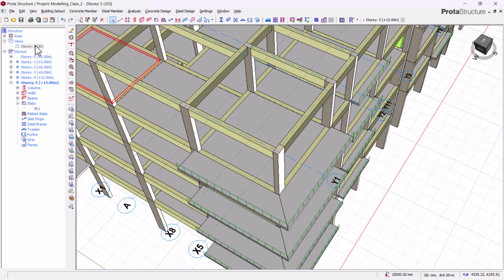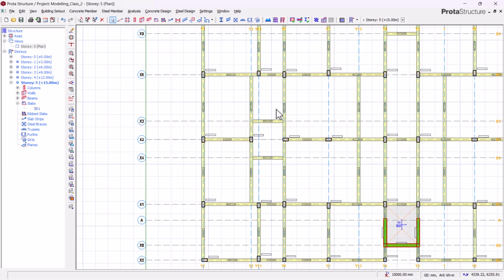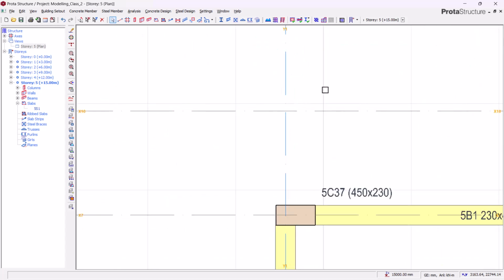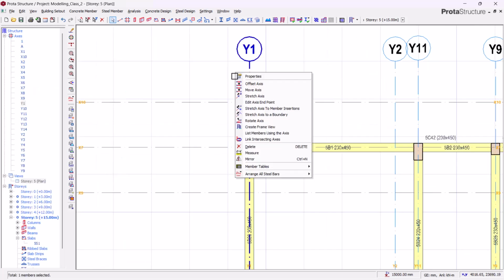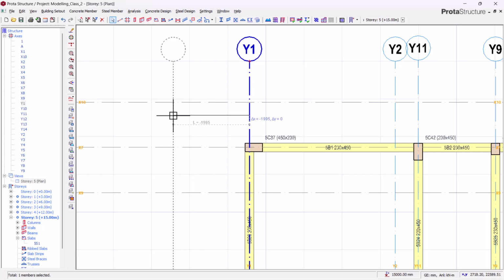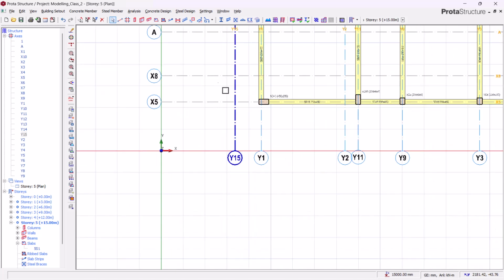Okay, and to do that, let's keep in mind that our beams, or our cantilever, has a length of 1.2 meters. So we'll come here and offset axis, coming towards this direction. We'll press F2 on our keyboard and type -1200, enter. Come back to this point.